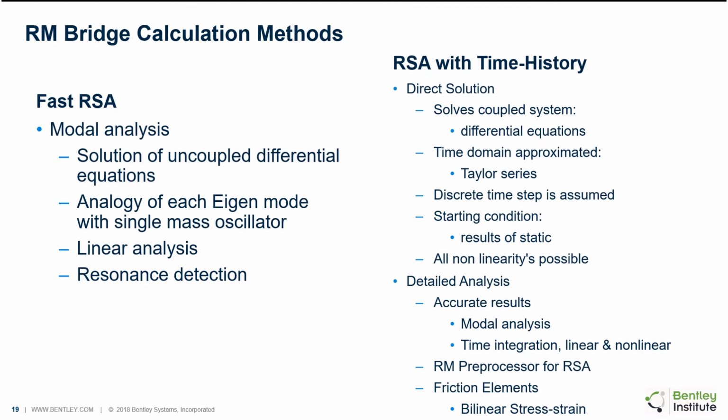Also with the fast rolling stock, we can get critical points and use these points in the time history. Because remember, at the very beginning we just have to pick a point in the structure, right, to say where I want to check all these values for design. So with the fast rolling stock, I can run the analysis, and it gives me some critical points that I can study and apply time history to that particular point. So then I can reduce the analysis time a lot, because I cannot do time history for every single point of the bridge, but I can do the most active ones, or the ones that I think could be affected. For example, a high speed on a curve.